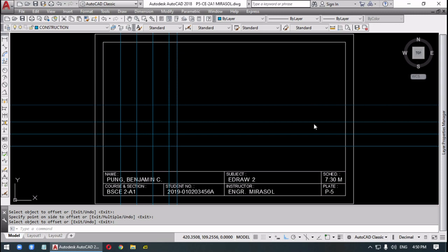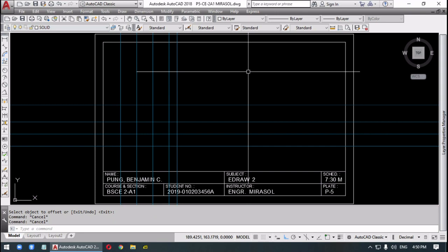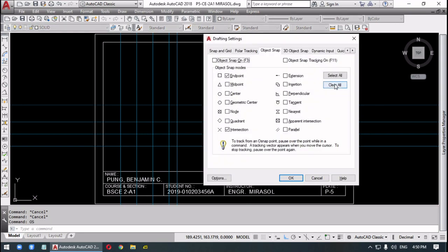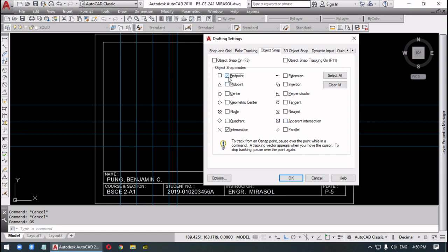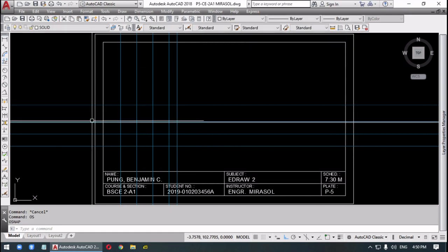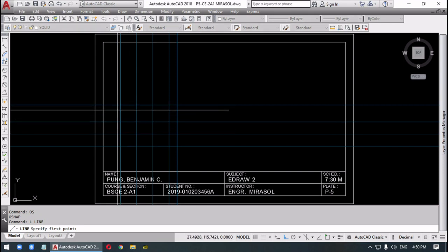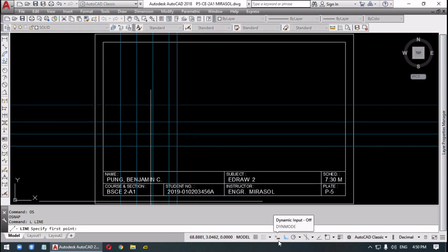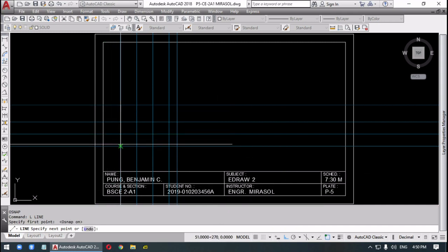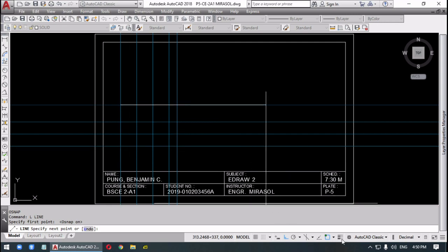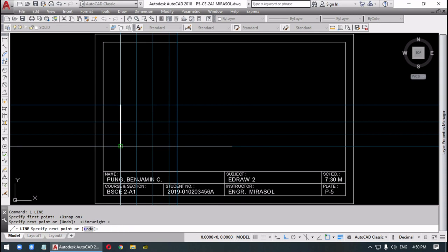Now that we have that, we can start drawing the face. On the solid layer, we will set the snap first. The snap should be intersection. There's the intersection. I also want to turn on the endpoint. Okay, so line, be sure that it's turned on. F3. I'll snap on there. So it'll be visible, I'll turn on the line weight.